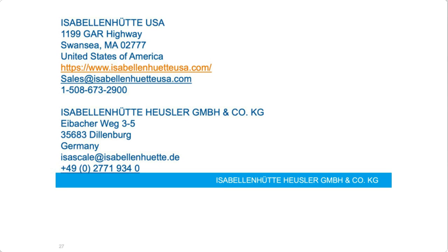And that's also important, we rate all our products with accuracy of reading. It means that no matter if you measure 100 amps or 1,000 amps, the accuracy will always be 0.1% of that reading. A lot of other manufacturers of current sensing products rate by range. That means you get whatever the maximum range is of accuracy out of every reading. So we don't rate our products like that.